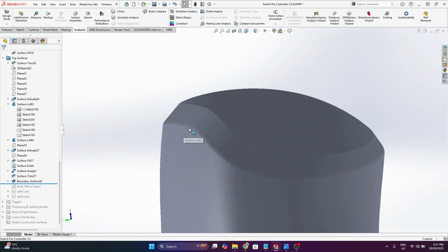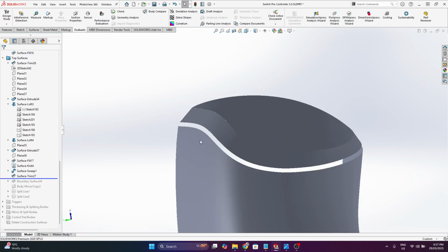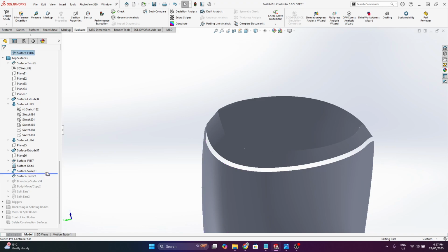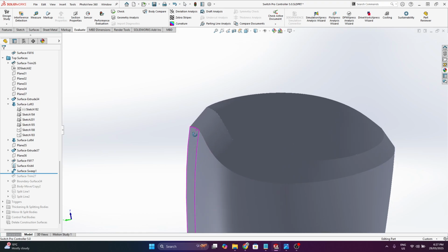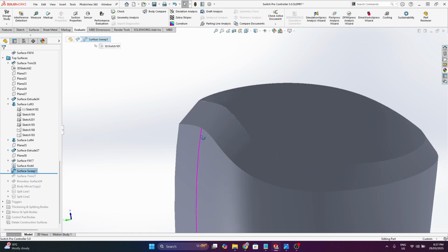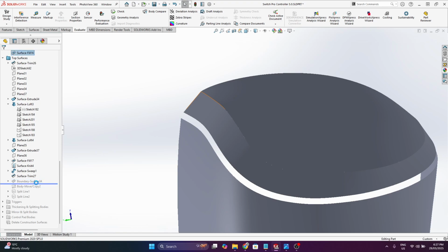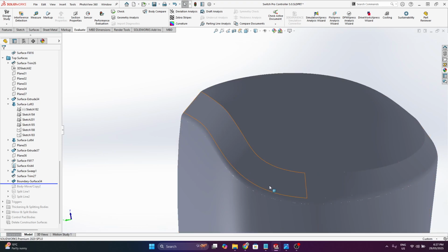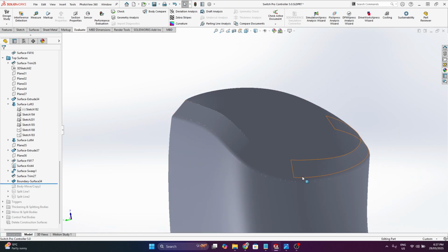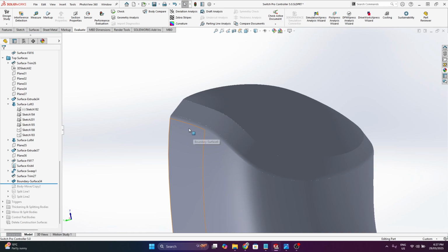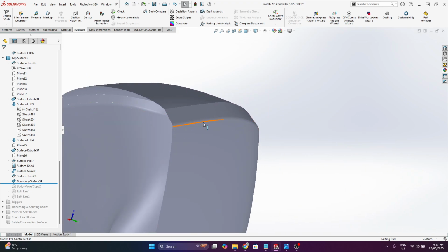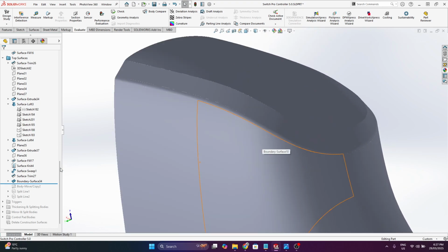Okay, so there's a small fillet at the transition here, which, you know, there are multiple ways to go about. I modeled it in with a sharp edge, and then swept the surface cylinder around and trimmed away what I didn't want, and then did a boundary surface between them, curvature continuous or tangency continuous, to get the fillet. You don't have to do this at this step. It depends what your intention is. You could make this less solid later on and then add this fillet in here, but I just decided to do it here. Add that fillet in.